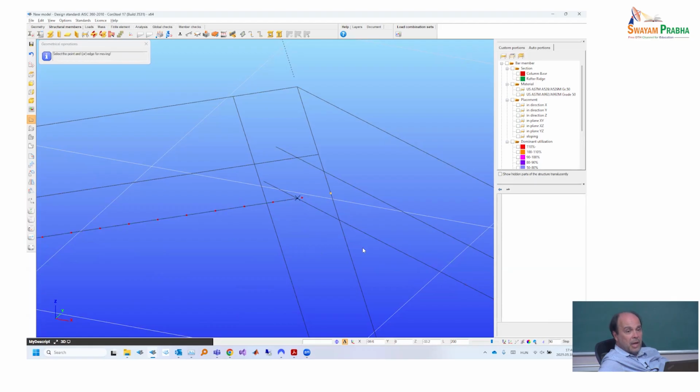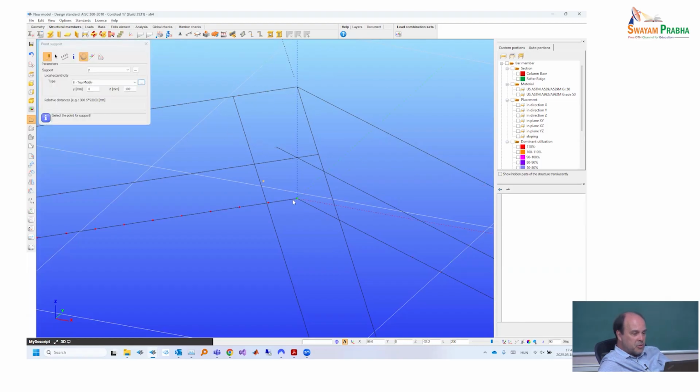And then I made the line shorter, and I can at the same time do also with the other line. I click on the end of the line and come back to the intersection. Now the lines will not be longer anymore. They will really have the end where I want. And now with this beautiful 90 function, I will be able to place the support really at 90.